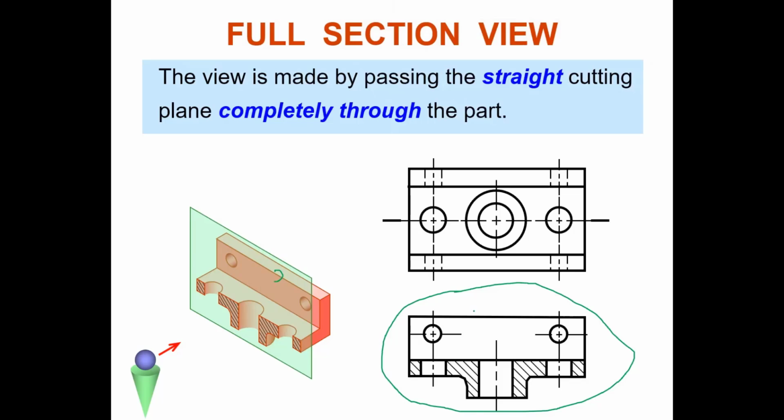But look at this front view of your orthographic. Are there any hidden lines? No. Yes, you're right, no hidden line. Even if, let's say, at the back I have some features there, here do not put them. Do you understand the rules? Even here on the front view, do not put them, even at the back. The idea is to make a simpler representation and to facilitate dimensioning. Okay, that's the rule: no hidden line.